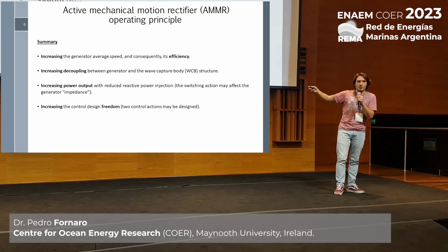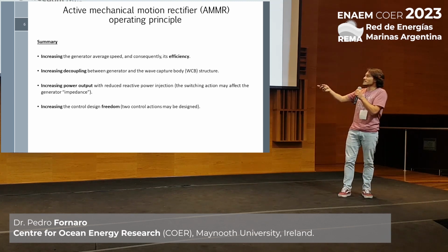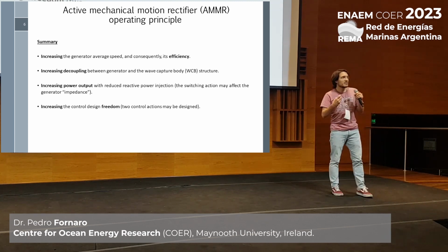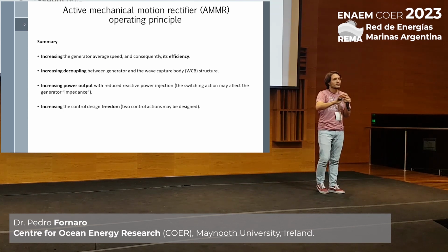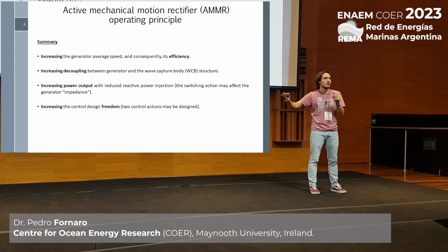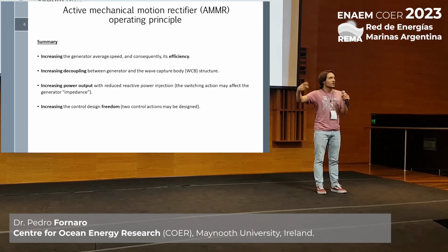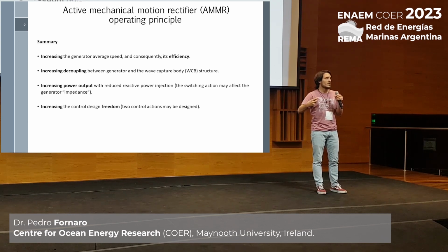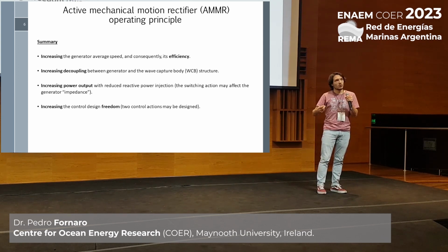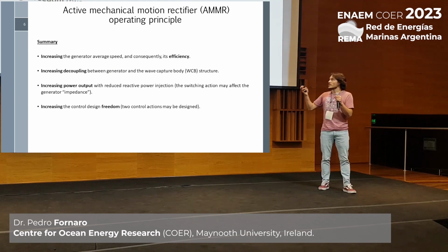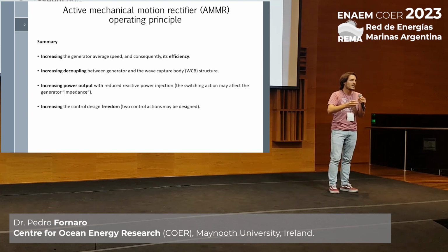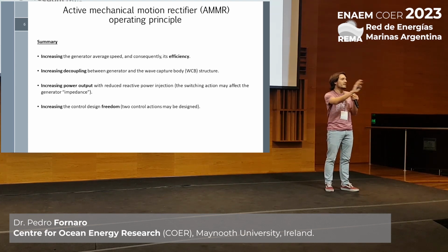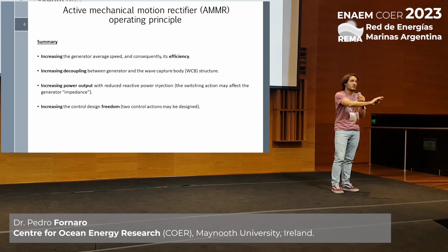And also, one thing that is very interesting is that we can increase the control design freedom. Typically, in wave energy devices, we have a direct connection from the device to the controller, and we have a generator torque which may be applied as a control action in the system. However, in this case, we have more control freedom because we can select the connection and disconnection instance in which both devices, the generator and the particular wave energy device, in this case we are considering a flap.